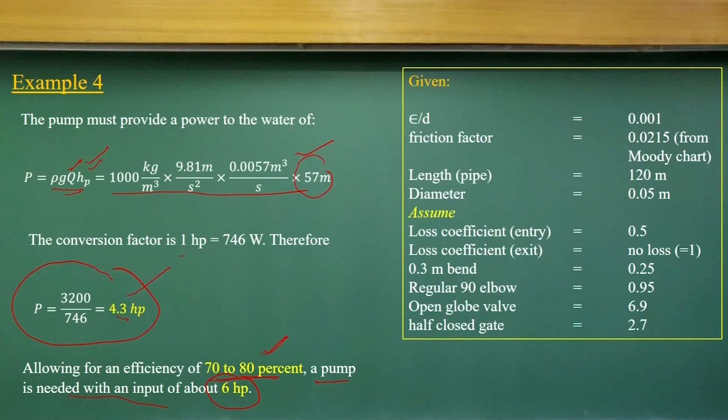So, this way we generally solve a design problem, designing the piping system with additional energy like pumping, or in hydropower projects we put in turbines. The basic concepts we use are the energy gradient lines, the Moody chart and specific equations to solve this problem. With this, let me summarize the lectures I discussed today.